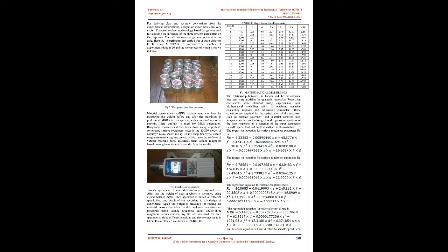[16] carried out optimization of process parameters in turning of AISI 1040 steel. Taguchi method was used for optimization. Experimentation was carried out under dry condition using coated carbide insert. Surface roughness and material removal rate were optimized by taking cutting speed, depth of cut and feed as the parameters of optimization. Cutting speed and depth of cut were found to be the most and the least significant parameters respectively while considering the surface roughness. K. Sharavanakumar et al.